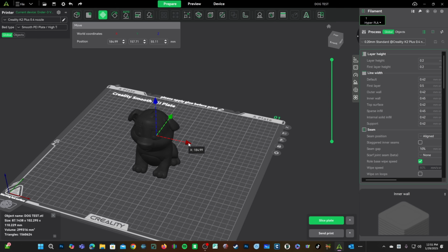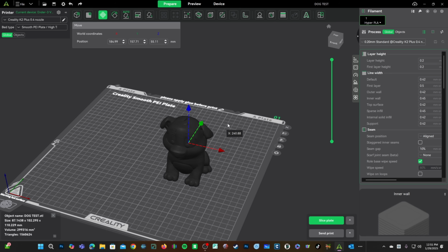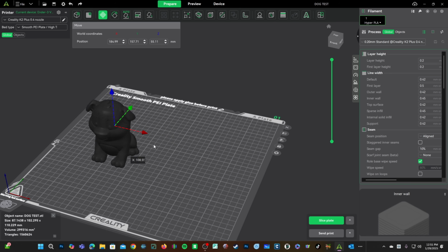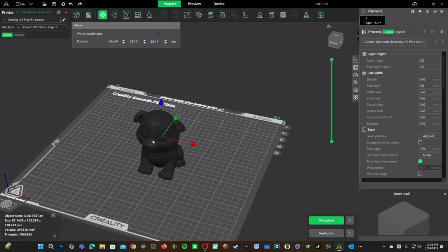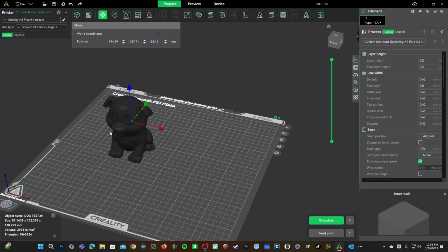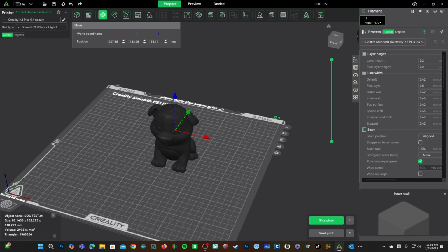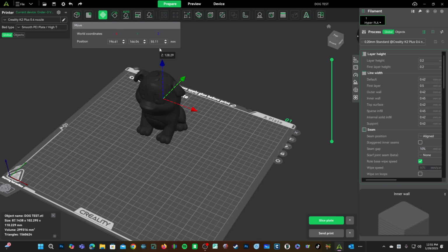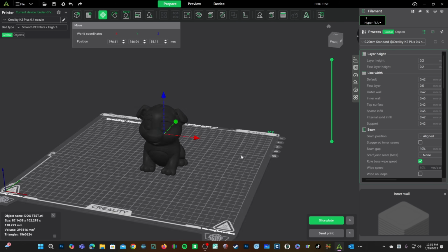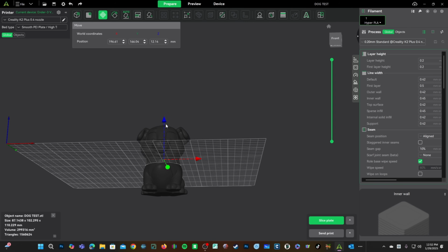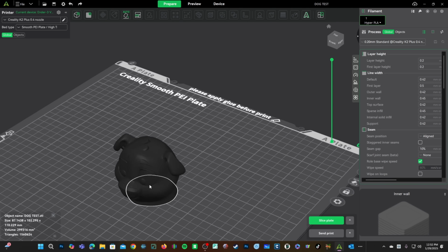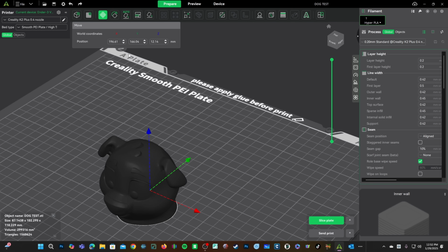Notice once I click that arrow, I can move my cursor away and continue to have this exact movement with no worry of going up, down, or diagonal in any way. If I grab just the model, I can free float this thing and I won't have that exact control. You may do the same up and down. Moving the model upward will snap it back to the bed. However, you may place the model below the bed, which will come in handy for many technical and troubleshooting purposes.